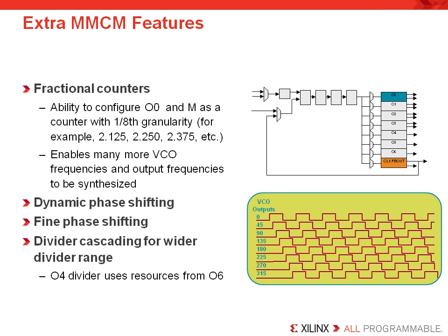Now, the MMCM also supports a dynamic phase shifting functionality, which allows you to actively phase shift the generated outputs based on a single input. The MMCM also supports cascading the outputs for a wider divider range.